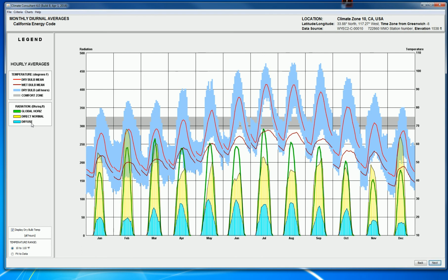As a matter of fact, when we finish this presentation, we'll run the same experiment. Do you see any rays coming through? Do you see any sunlight coming through? But yet there is light coming through, right? That is diffuse radiation. Okay? So if it does not cast a hard shadow, it's diffuse. If it casts a hard shadow, it is direct radiation. Okay? You have 3 of them. The global horizontal is the combination of the 2 put together.